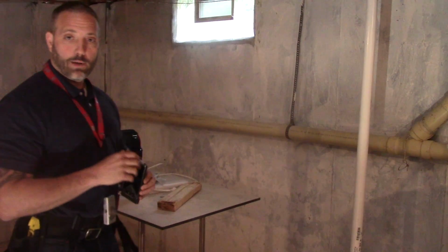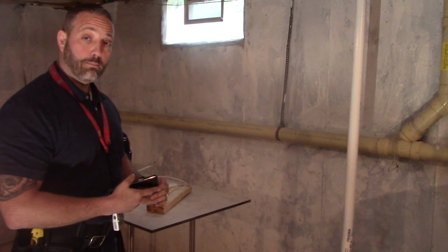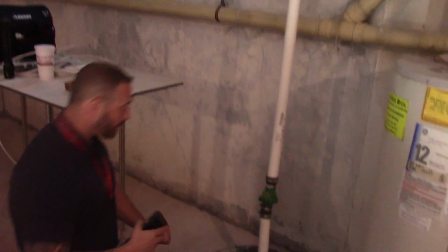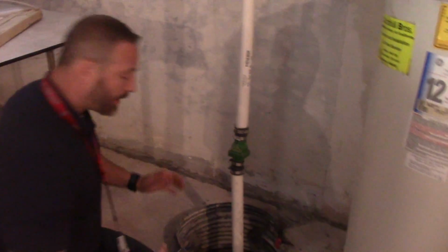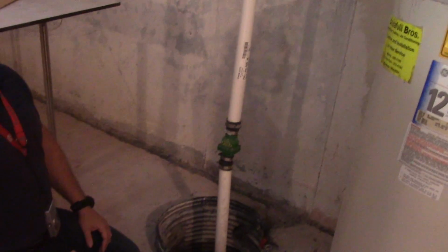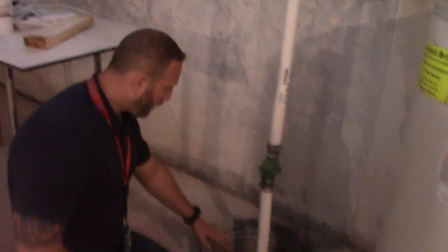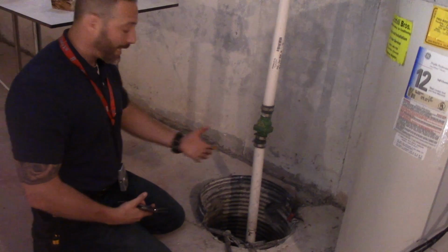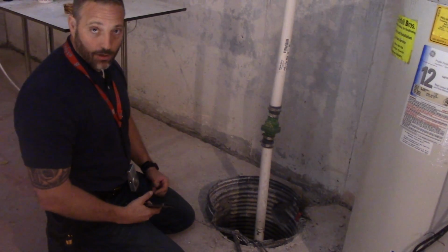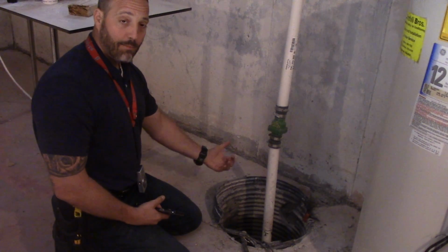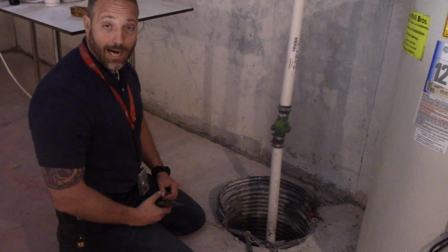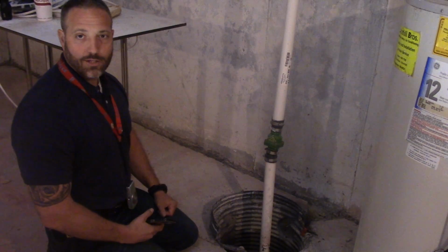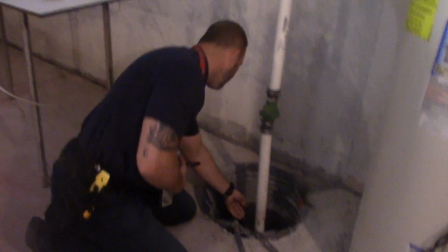Now the last element we're going to be looking at is the sump pump. So what we're going to do is get started looking at the sump pump. And again, you always have to make sure that you're in a safe environment. So here we don't actually have any water in the sump pump. So I feel confident that I can reach my hand in there and touch the wand and move it. I want to see if I can actually operate this sump pump. If there is no water, we just want to see if it's going to kick on or not. So let's do that.